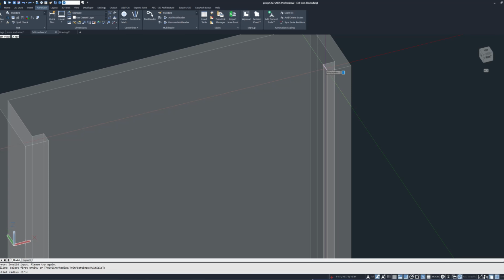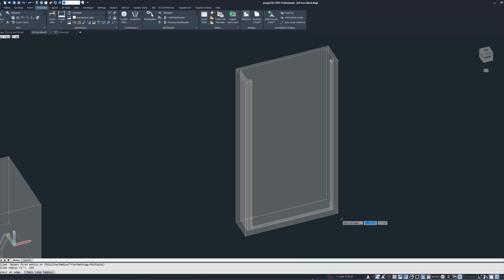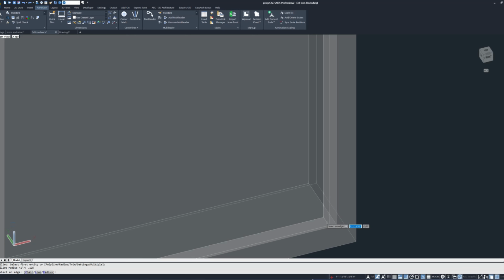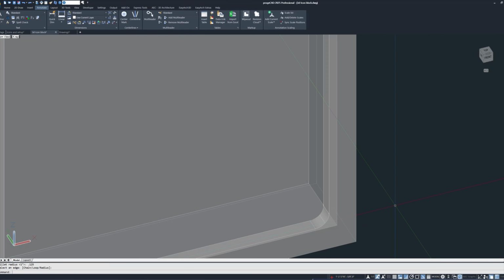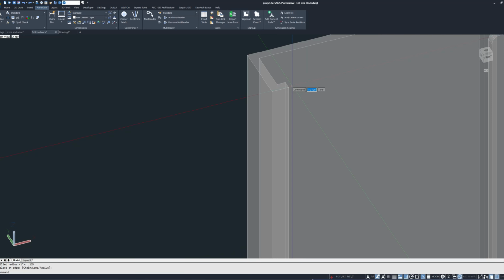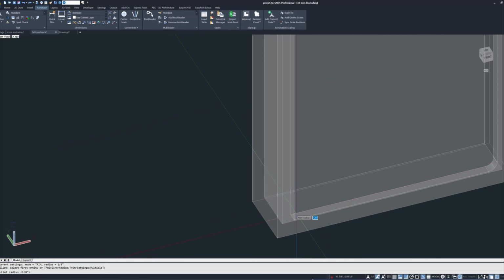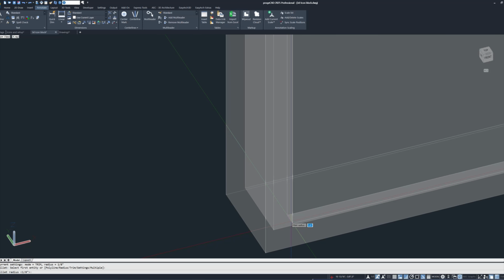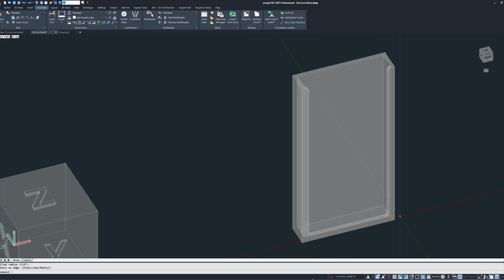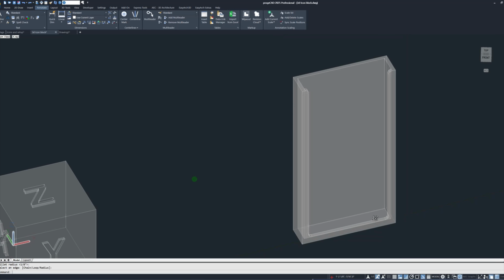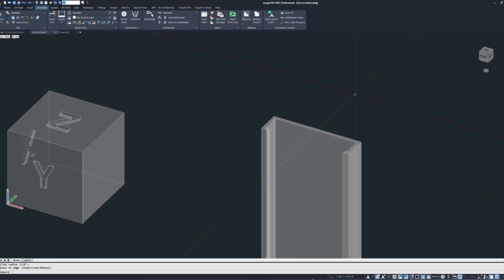In order to use it correctly, we have to have two corners selected. The fillet command will ask for a radius, then selection of one corner, then another. The corners must be adjacent to each other. Do the same for the void space corners. Now spin the object again to see if it matches your specifications.